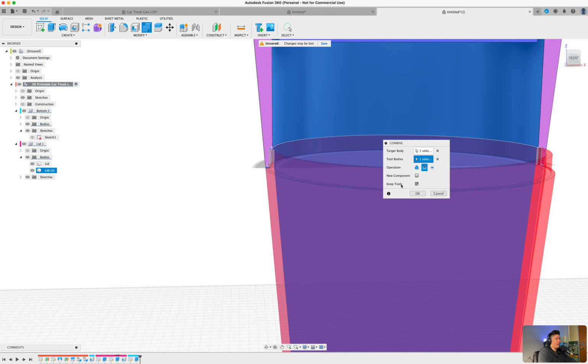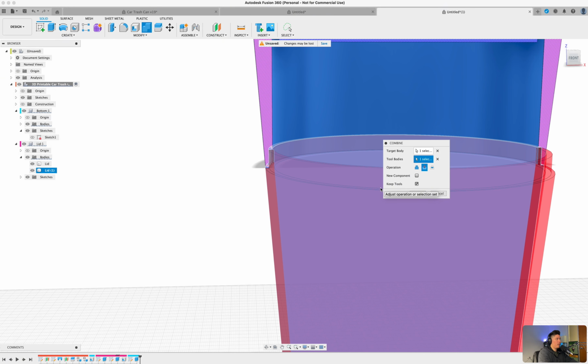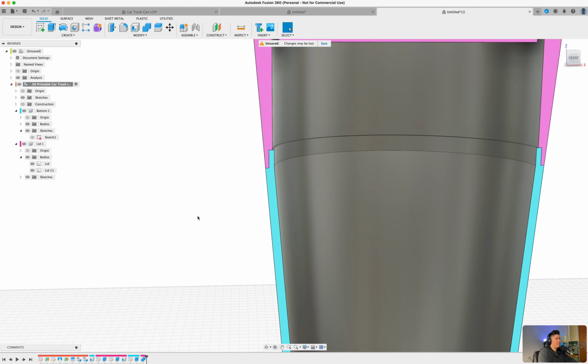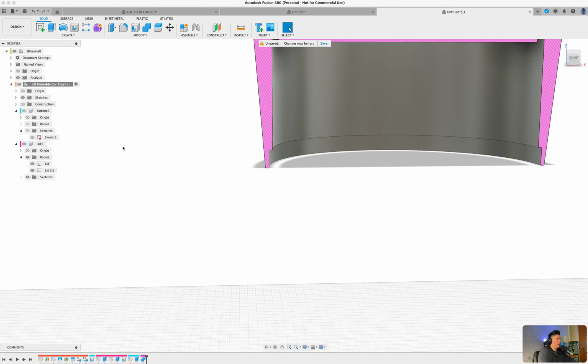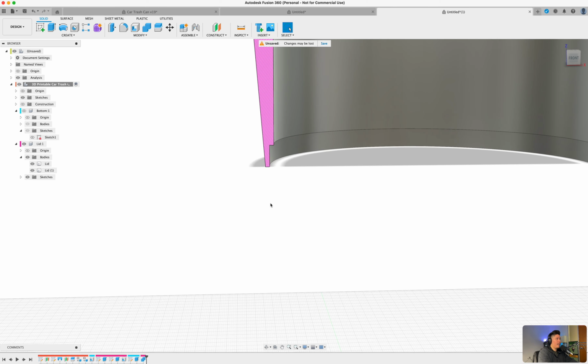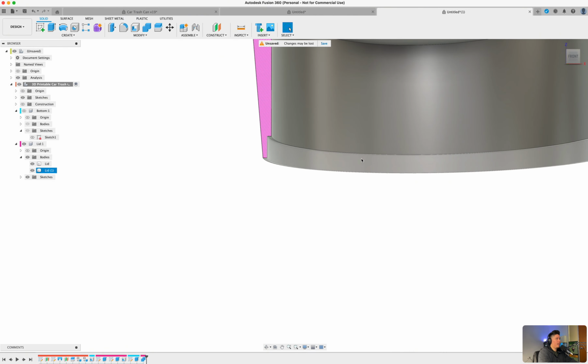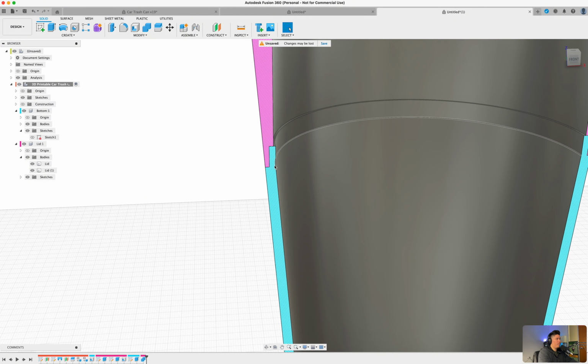After that, press OK. From here, if we take a good look at our design, if we toggle back off our bottom, now our lid has a little bit of a gap in between here that perfectly aligns with our design at the very bottom. Now, as of right now, although these technically fit within Fusion 360, they still wouldn't actually fit if we 3D printed them, or if we tried to, it'd probably be a really tight fit, and it probably would not be an enjoyable experience.